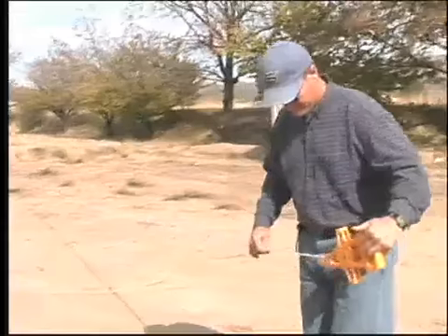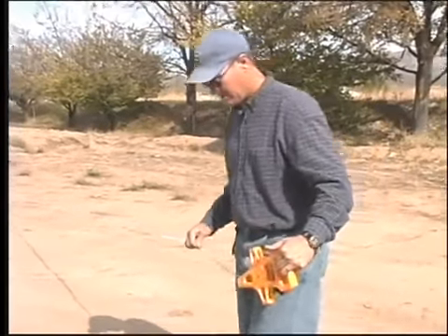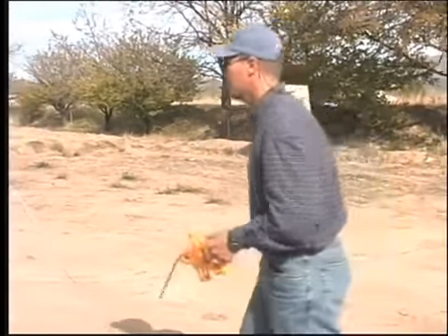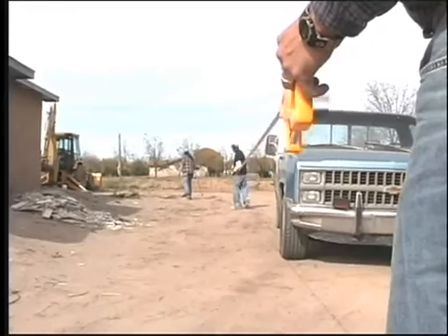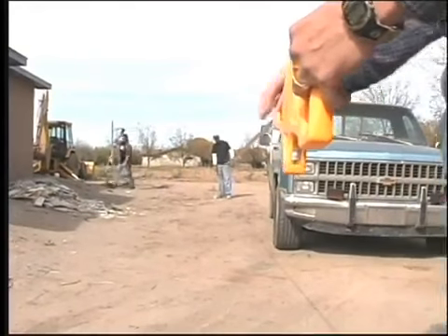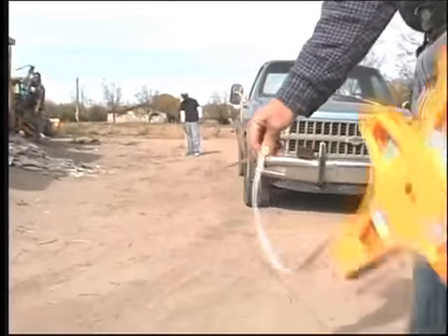Some manufacturers claim a chamber drain field can be sized smaller than a gravel and pipe drain field. Do not reduce the size or length of the drain field when using the chamber system. This may lead to early drain field failure. The drain field should be sized the same as for a gravel and pipe system.